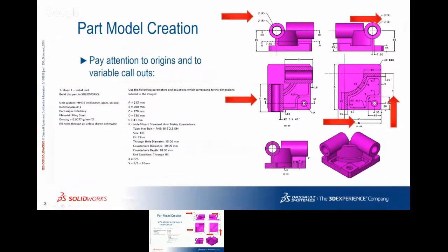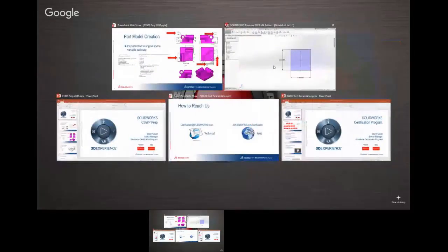So if we look over here, it's 35, but that's just that little tab area. The rest of it is at 25. My brain tells me to just extrude it at 25 and then add that other boss later on. It's easier than trying to go all the way up and then cutting the rest of the area down, right? Seems simple enough. Can I ask a question?